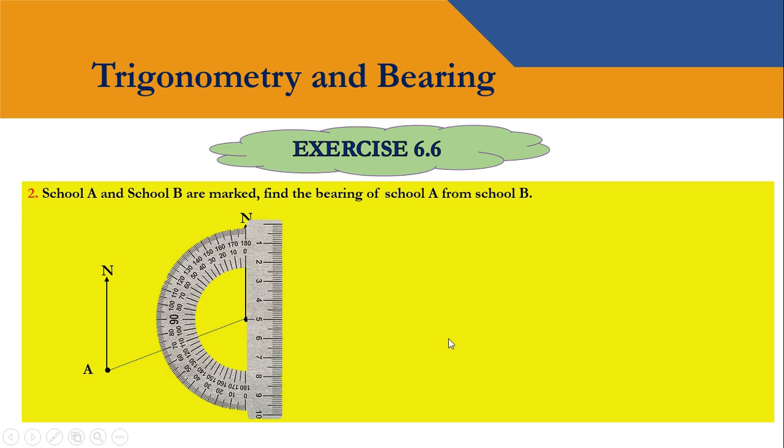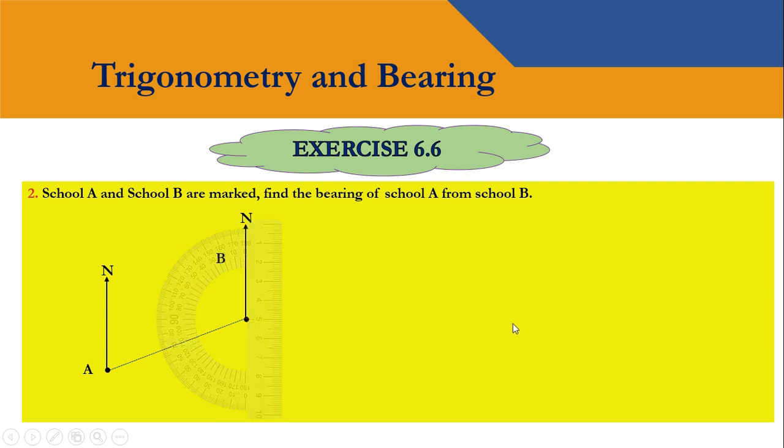Now again place the protractor in the opposite direction and read the remaining angle which is equal to 70 degrees. Now add 180 and 70 degrees. The bearing of school A from school B is equal to 250 degrees. So that's the answer to this question.